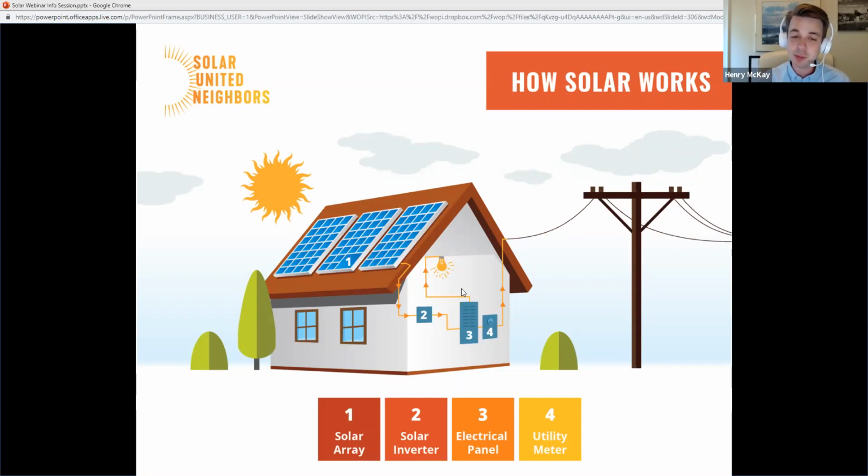But if you had built up bill credits during the sunnier times of year, you'll instead spend down those extra bill credits. So this is a process where, even though it's not evenly sunny all year, you could build a solar system that covers your entire year's worth of energy usage, because you can overproduce in the summer, bank up credits, and then use those credits during the less sunny times of the year.